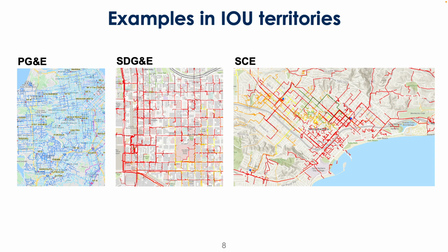Yes, absolutely. Those configurations, it's not like one utility does one thing and one utility does something else. The demand for particular configurations is based on reliability needs and cost trade-offs. So certainly, for something like a hospital or any infrastructure that requires critical reliability for electricity, oftentimes you will find that the design of the distribution system for those end-use needs might be different, right? They might be operating with a series of loops or in these parallel configurations.